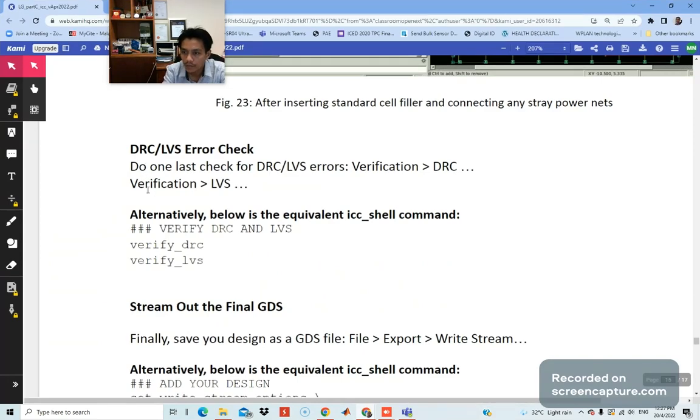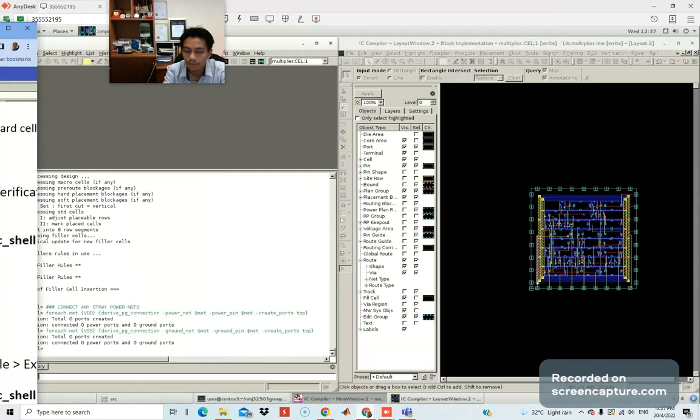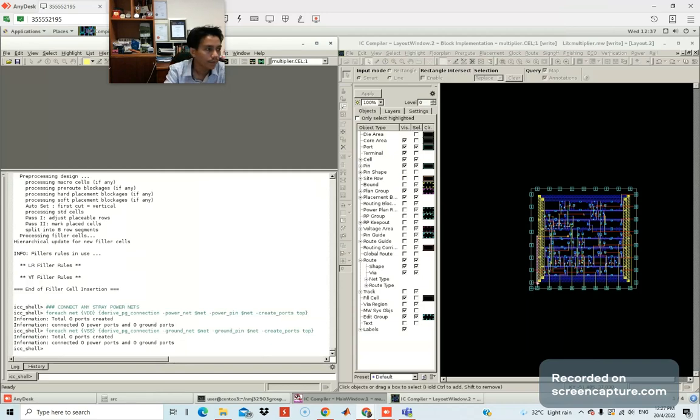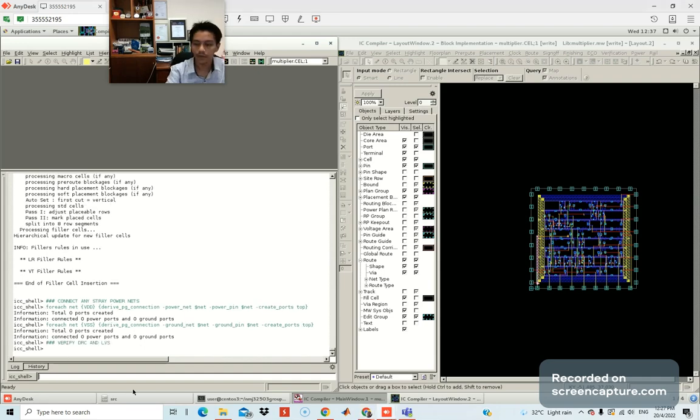Then we do the DRC LVS check. Okay, we go to DRC. Put it in here and enter, just a comment.